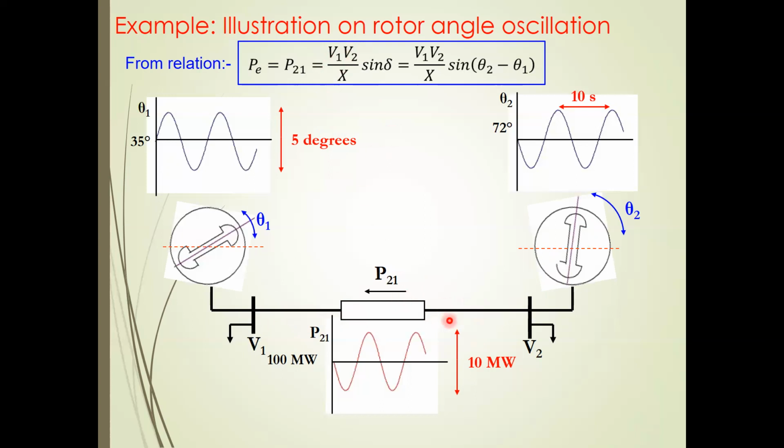So that's the power flow in the line. Let's say the bus voltages V1 and V2 are almost constant. Because the power flow is from bus 2 to bus 1, I will consider this bus voltage as the reference value, 1 per unit. Since this is the direction of the power flow, what will be the voltage here with respect to this 1 per unit? Maybe something like 0.95, 0.98, 0.99. So that will be the voltage difference between the two.